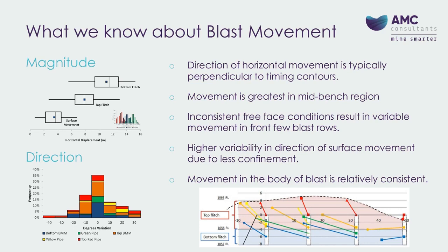Okay, so all these measurements of blast movement, what have we learned? What do we know about blast movement? What we've found by a number of authors and by studies conducted by myself as well, is that the direction of horizontal movement is typically perpendicular to the timing contours. We've found that movement is greatest in the mid-bench region of the blast.